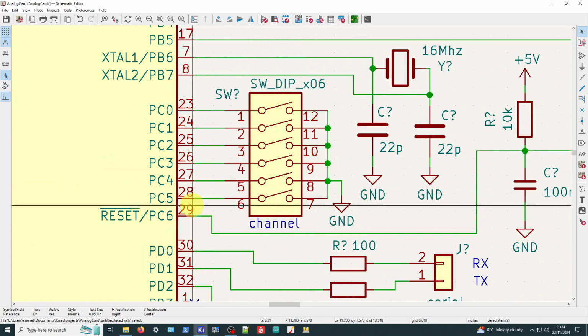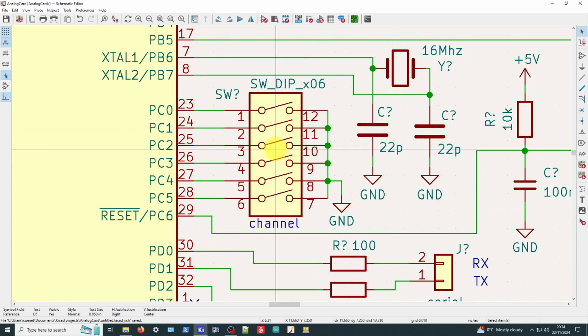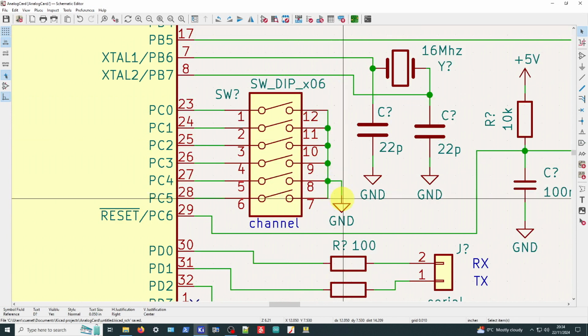We could have done a software solution where you program the chip, which then you could actually sort of remotely change it. And we could do that later. But for now, just to keep things simple, I thought, no, we'll just put on a very simple DIP switch. And you use a fine point prodder or a screwdriver, and you just flick the switches to the channel selection that you want. They all go to ground, and basically these are actually pulled up high internally through the firmware.